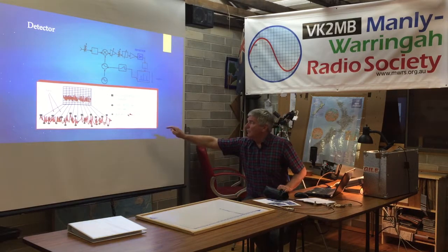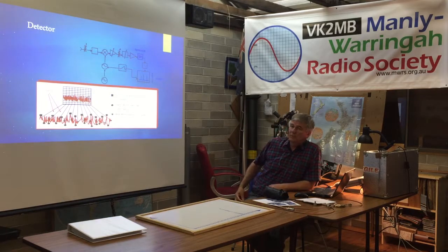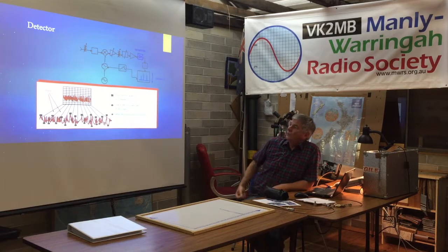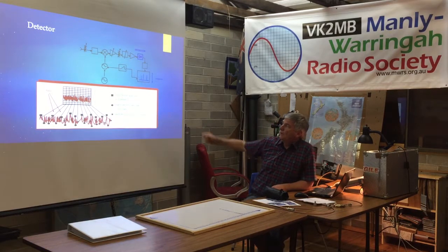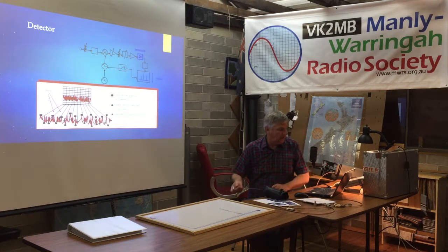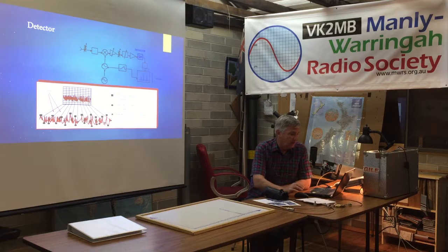That says last value, but a sample detector doesn't necessarily need to be the last value. A sample detector just takes one sample at random within that bin. And there are other detectors, but that's just some of them. So you can select different detectors, again, depending on what you're trying to do. And I think I'll leave it there.